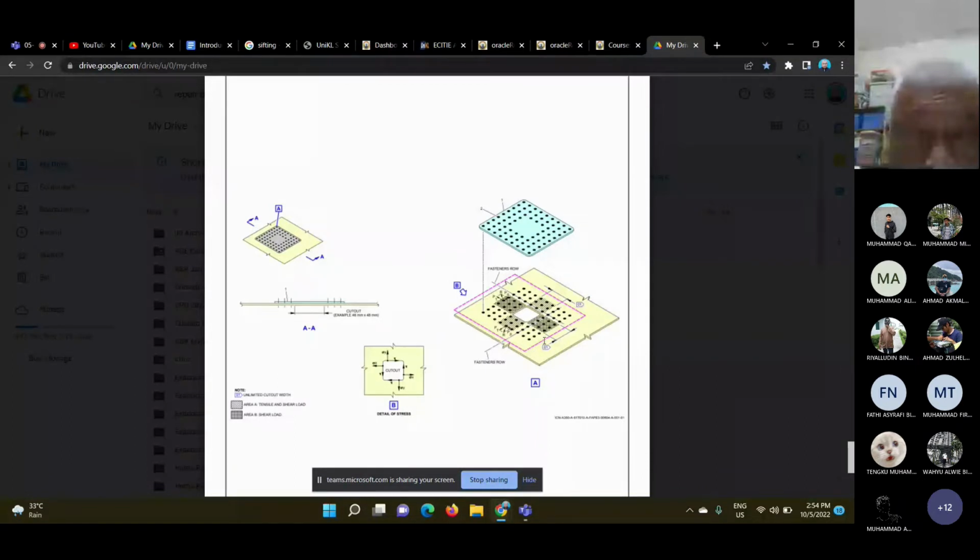and we don't make this repair complex because it's not a flush repair, so this area will not be in the area that is critical for aerodynamic smoothness. If the area is critical for aerodynamic smoothness, then we cannot have just a doubler patch repair like this.